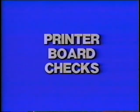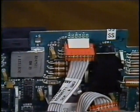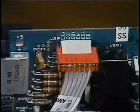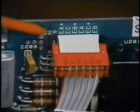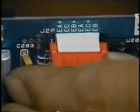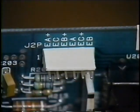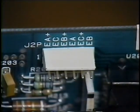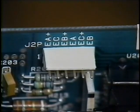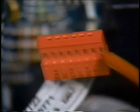In this section, we will discuss some of the diagnostic checks done on the printer board. First, let's locate the connectors on the printer board. This is the transport motor connector J2P. Note that there are 6 pins on the printer board. But there are 8 pins in the connector.